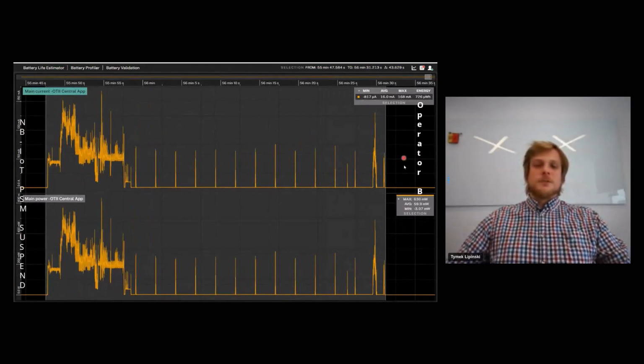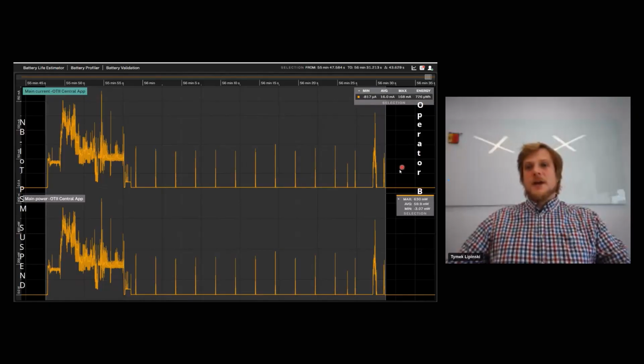And this is operator B, the one with 1 second RRC keep alive. This time we are not using the release assistance indicator, and the active time was very long. So let's go through this scenario again. 4 microamps of current, system initialization, loading, searching, sending, receiving, 1 second of RRC keep alive, and we end up releasing the RRC.